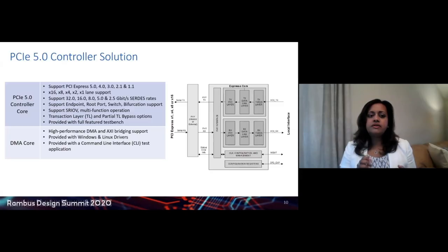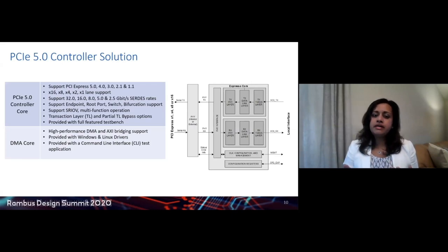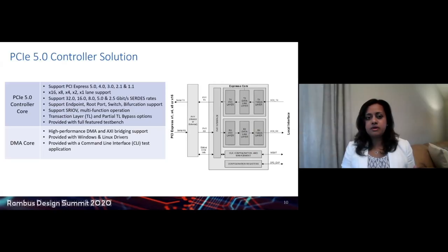We also provide very comprehensive application support, which includes endpoint, root port, endpoint/root port dual mode support, switch, and verification. And for most customers, a full transaction layer meets most of their needs. However, for customers needing transaction layer bypass or partial transaction layer options, we also offer that as part of our solution. And the core also supports SR-IOV multifunction operation.